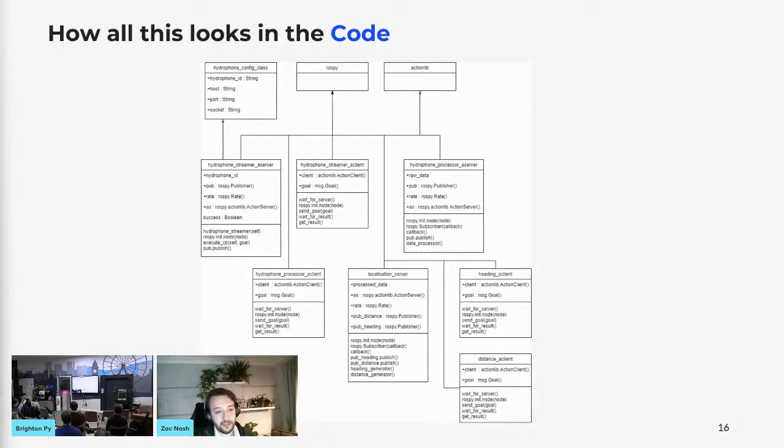That's then called, and that turns things into a localization. From there you can get heading and distance, and you do that using triangulation. So where is it in relation to the three hydrophones we have, and how long did it take to get there? If it took less time to get to the left one than it did to the right, then you know it's on the left, that sort of thing. So this is all information that's needed to infer behaviors.